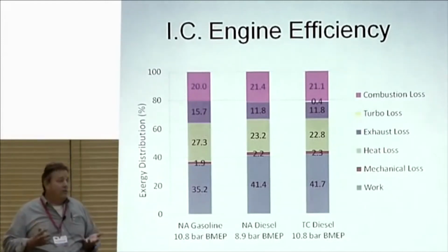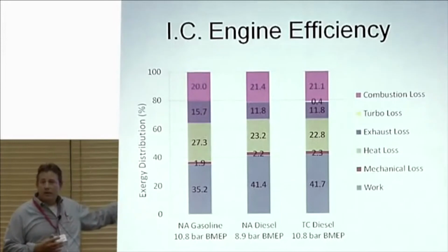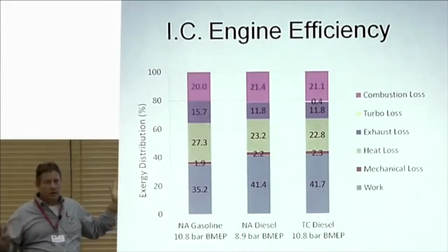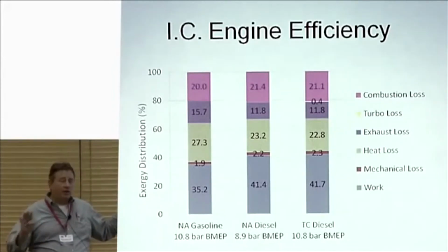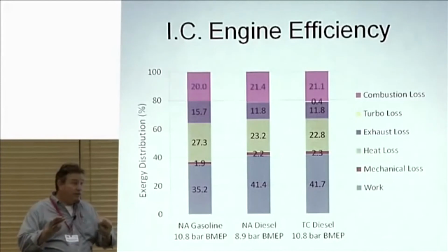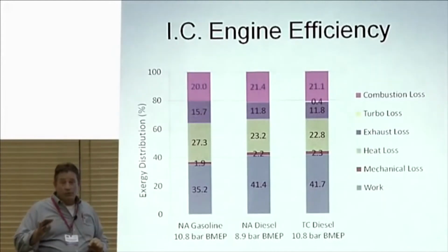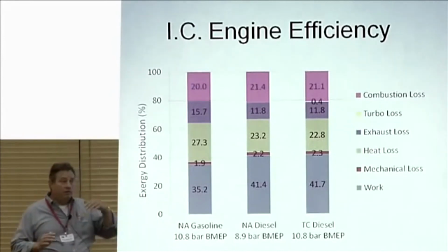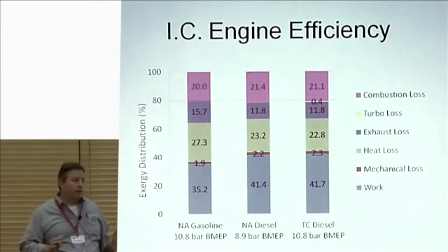We've got to do something smarter because this is thermodynamically nuts. And the idea that you're going to put thermoelectrics on the cooling jacket or even on the exhaust system, I'm sorry, is just not a good idea. Because you have a Carnot cap to begin with, and then you have a ZT figure of merit that typically will put you down at 50%, 40%, 30% of the Carnot cap until you get ZTs that are at least 4 and maybe more like 10. It just doesn't make any sense to do that.